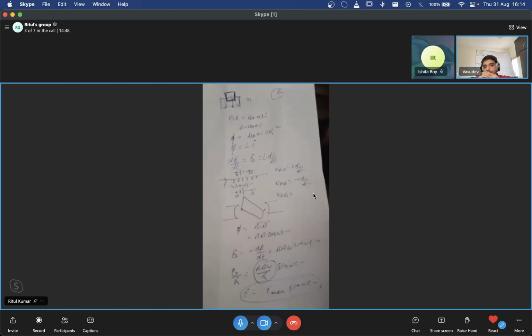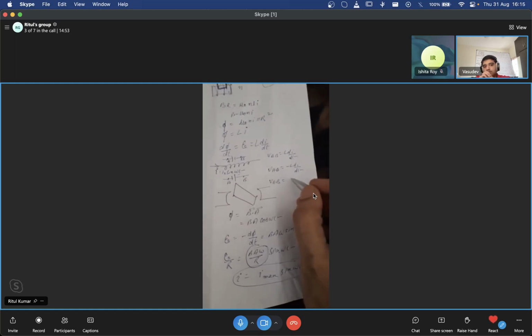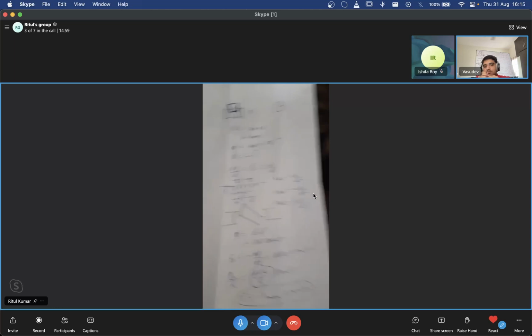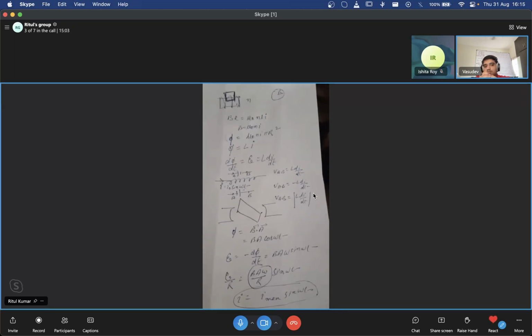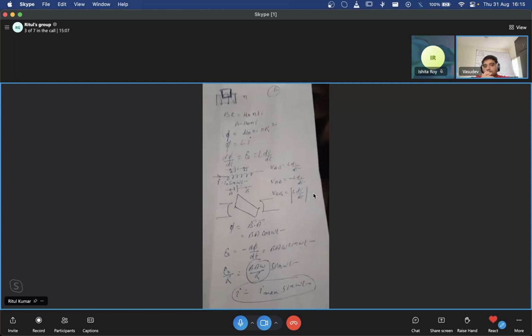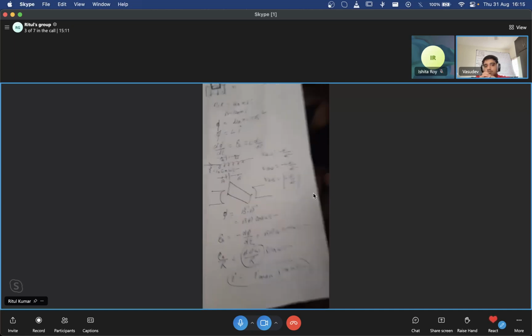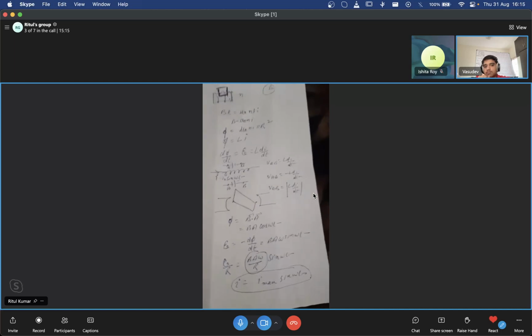Why do we have these suspicions of doubts? Because the correct equation is not known to us. The correct equation in this case is VAB equal to the mod of L di by dt. It should be correctly mentioned. And in accordance, you have to change, whether the current is increasing or the current is decreasing. If it's increasing, it will take the shape L di by dt, decreasing, minus of L di by dt.